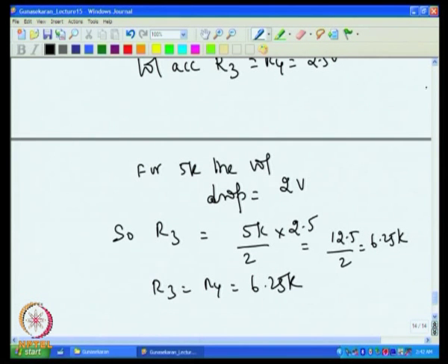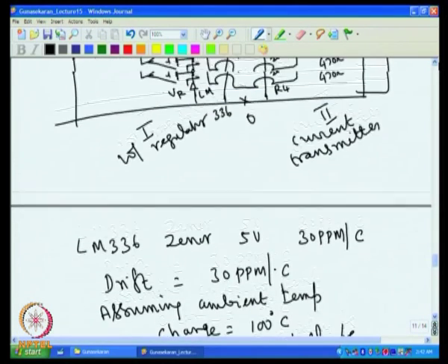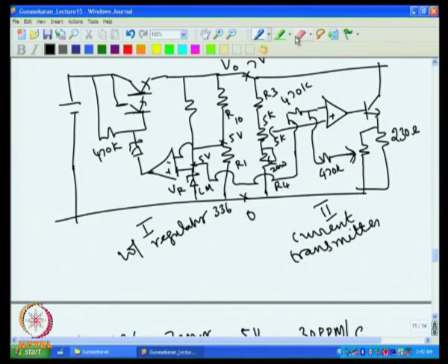Our interest is to compute the voltage change at the potentiometer point. If we take this potentiometer, assume that it is at the maximum, say at 20 milliampere, then the voltage at this point is 4.5 volt, because this is taken as 2.5 and the voltage across this is 2. Now at 4.5, what will be the change, because if this voltage changes by 25 millivolt, that is what we have calculated, then what is the expected change at the midpoint.